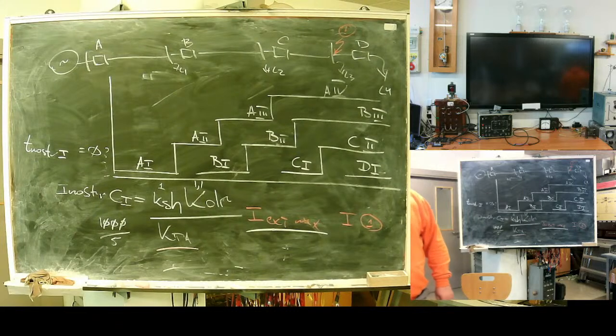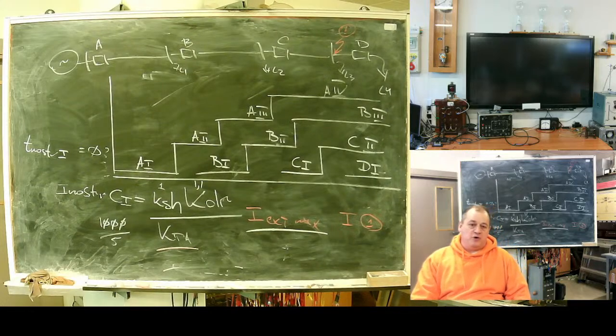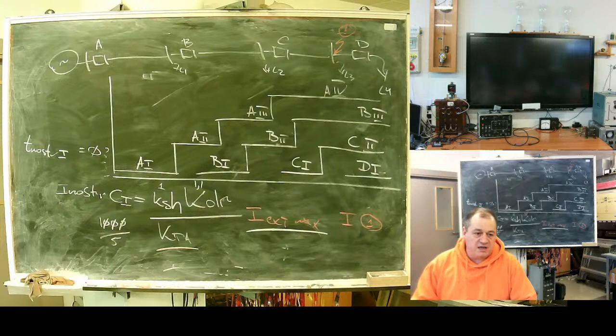For this case, to prevent false trip when surge arresters operate, you need operation time longer than the expected current flow time from surge arresters. Longer than surge arresters operation time.